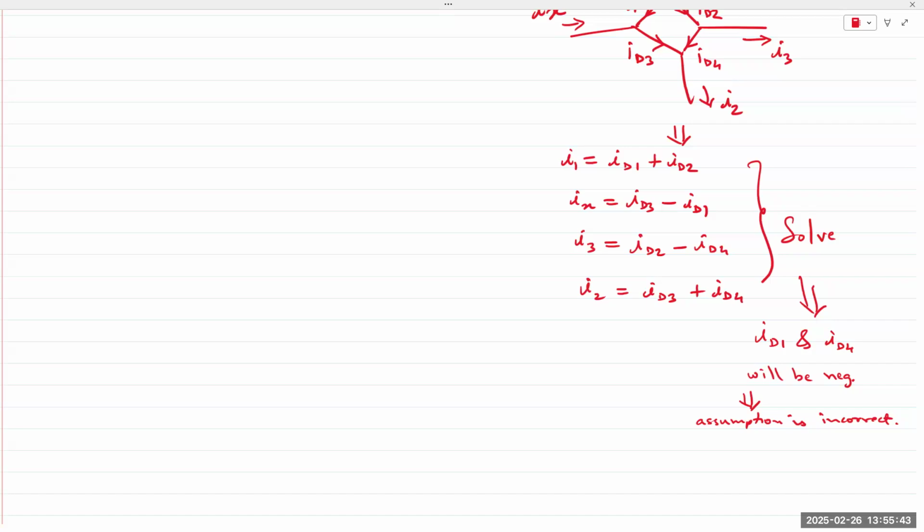We can do that. And that, I will tell you, is very easy, because if all diodes are off, it's an open circuit at that node. It results in 2 separate circuits, and it's very easy. Boom, done. But you need to then apply KVL and calculate the voltages. Okay.